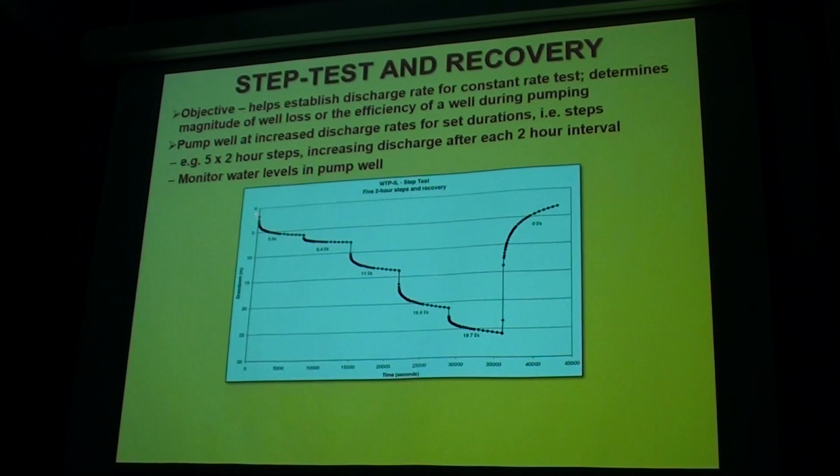You can see when you first start pumping, or you first increase the rate, the level drops quite quickly and then begins to level out. Okay, 2, 3, 4, 5 steps for this one. Then you turn your pump off and you measure the rate of recovery within the well.